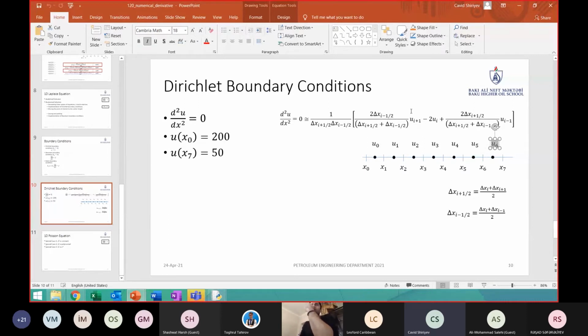And in all our calculations, we are assuming that we are solving for the unknowns at the center of the grid. Okay, we are not solving at the nodes, we are solving at the center of the grid. And it's not necessary that we'll have the same size elements. There can be differences in the sizes of the elements as well. It's not important that they are constant.